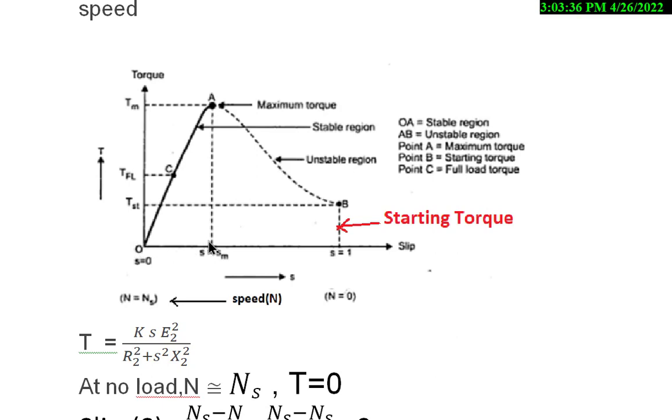If you observe properly, in the linear range of the three-phase induction motor torque slip characteristic, as the load increases, torque increases, but speed reduces, that is, slip increases like this. It continues like this till it reaches the maximum torque.